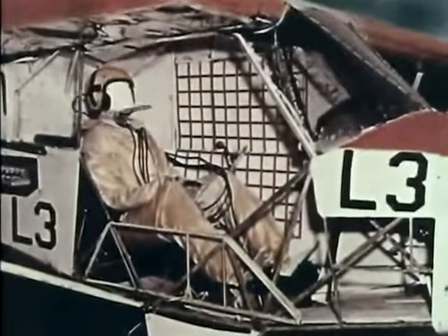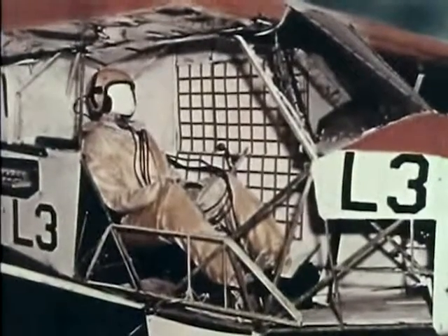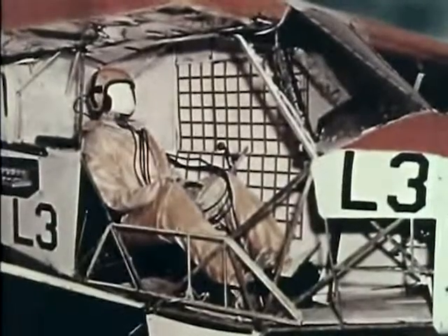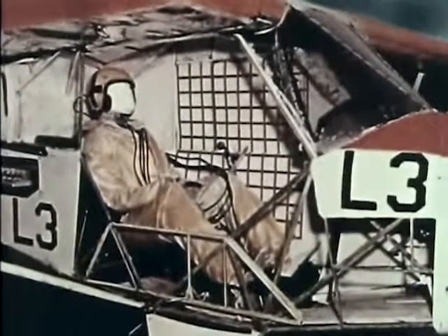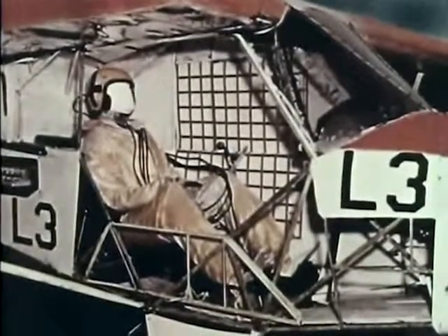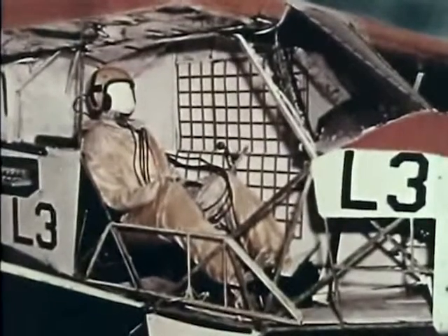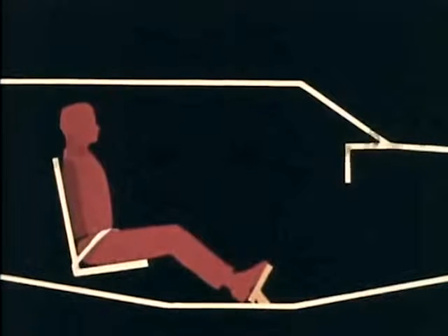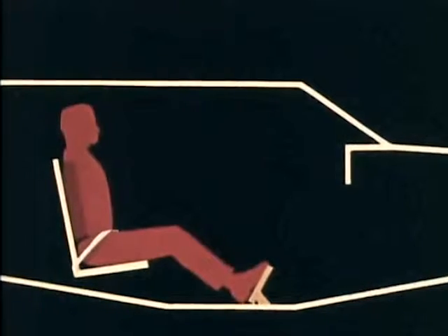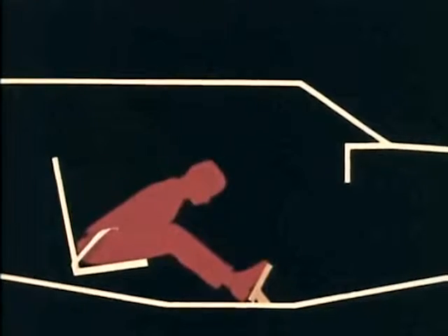If an occupant is not to be injured when wearing only a seat belt for restraint, sufficient space must be clear ahead of the occupant to allow him to flex over the seat belt. The occupant in this airplane was restrained by only a seat belt. The front seat and rear control stick were removed so that there was sufficient room for complete flexure of the dummy's torso. The torso of the dummy moved forward and downward until the chest contacted the thighs.